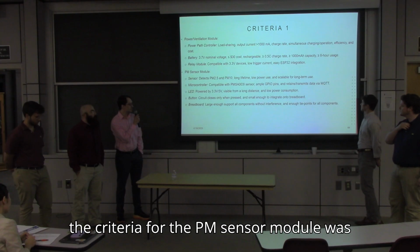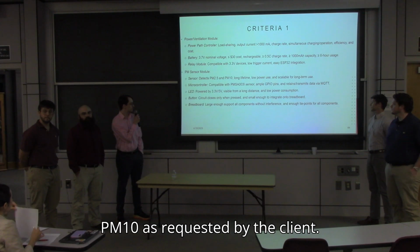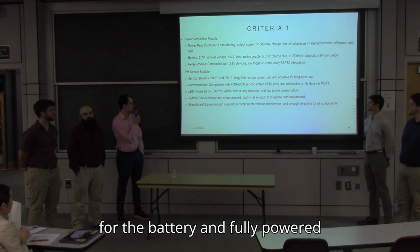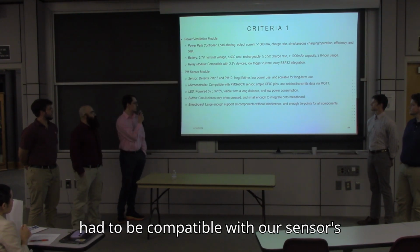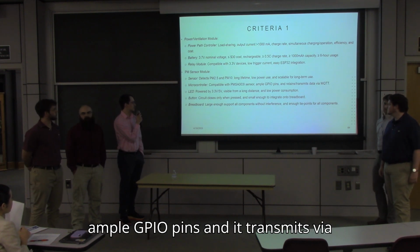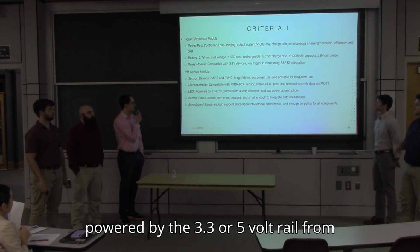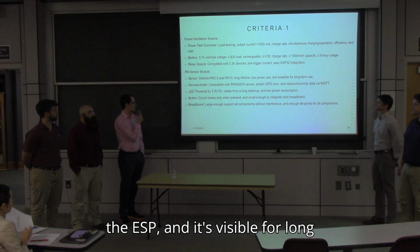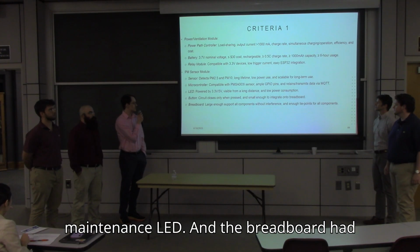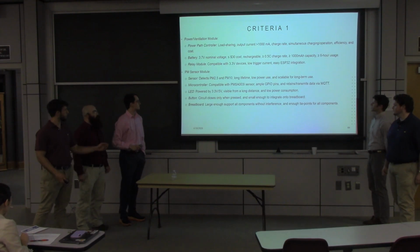So the criteria for the PM sensor module was that the sensor had to detect PM 2.5 and PM 10 as requested by the client. It had a long lifetime and low power use for the battery to fully power it throughout the day. The microcontroller had to be compatible with our sensor's interfacing method, which was I2C, have ample GPIO pins, and transmit via MQTT. Our LED had to be powered by the 3.3 or 5 volt rail from the ESP, and visible from a long distance. The button closed the circuit only when pressed to deactivate the maintenance LED. And the breadboard had to be large enough to support all the components without interference.